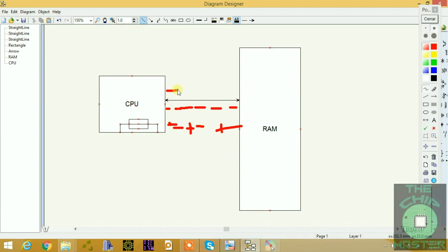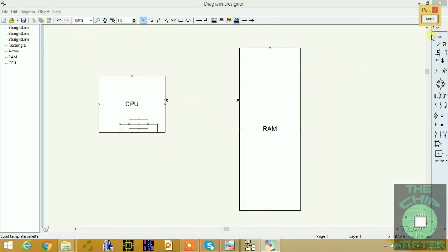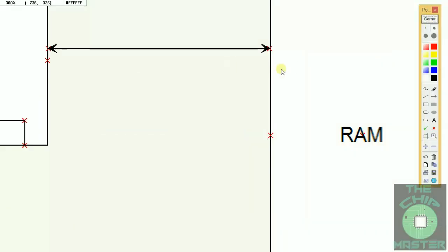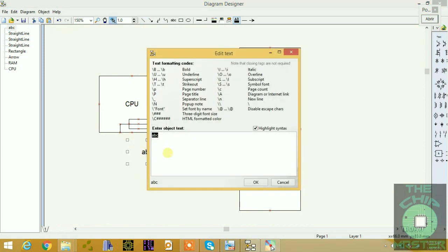When the CPU is returning that information back to the RAM, if the ODT section in the CPU, in the memory controller, or the RAM termination resistors and section inside of the RAM is not working, then the signal will be gone. When the CPU transfers the signal back to the RAM, the data will be lost. So this is why you have an internal resistor inside of the CPU, and a termination resistor on the RAM, right, to prevent this, and this is known as